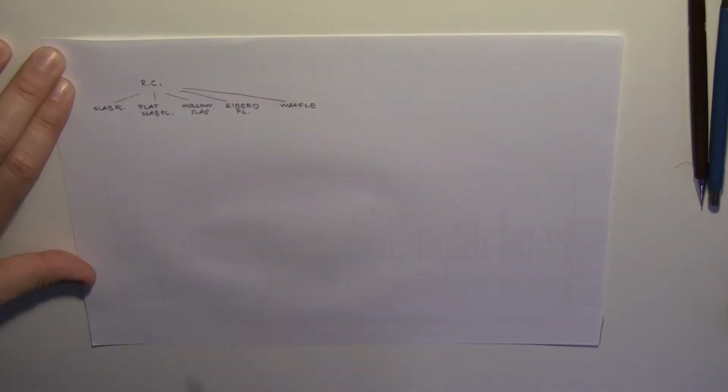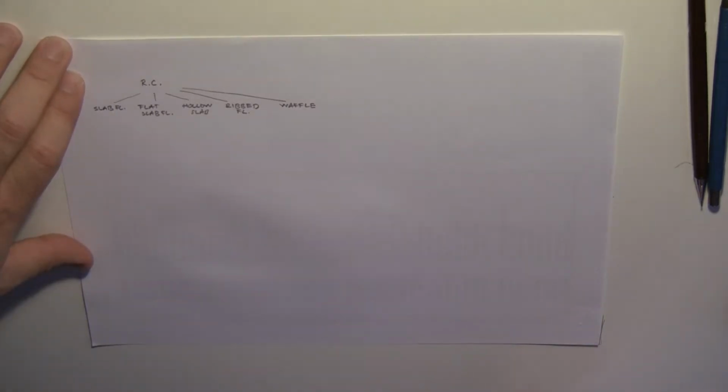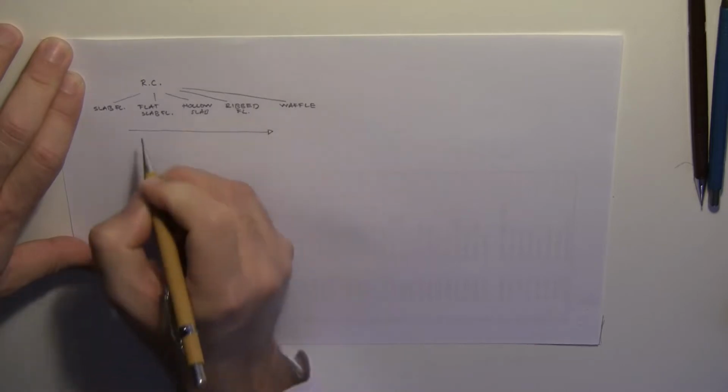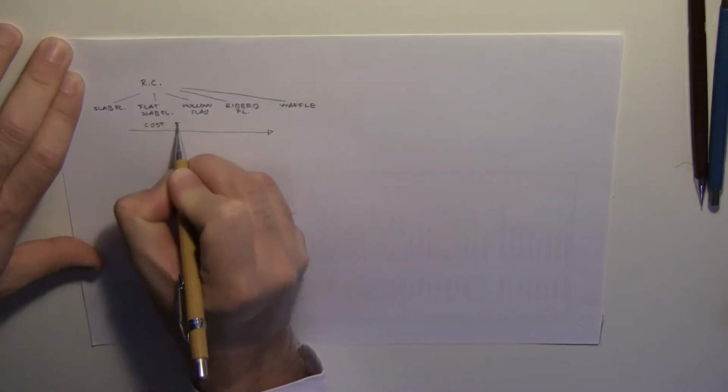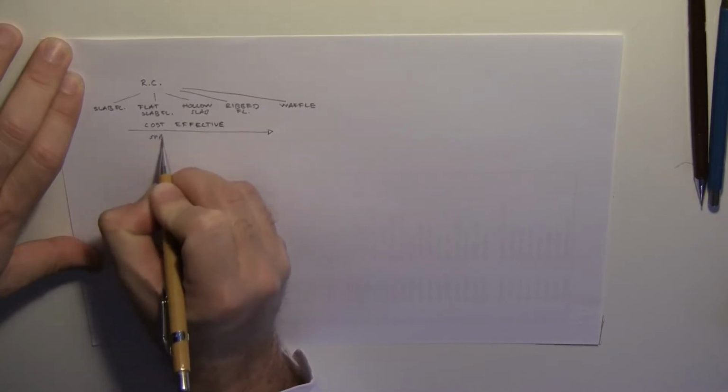We have talked about these. These are the most common types of reinforced concrete floor systems. There is not a rule book about these. Different professionals, different civil engineers may name them differently, or different architects may also make this categorization differently. The important point is how we use different types of reinforced concrete structural systems to pass larger spans in a more cost-effective way. So from this floor type to that floor type, the cost-effective span passing capacity increases.